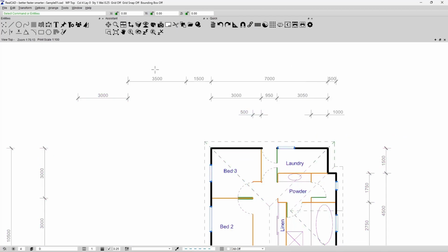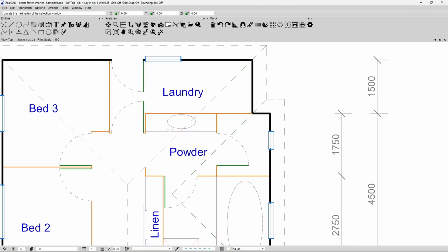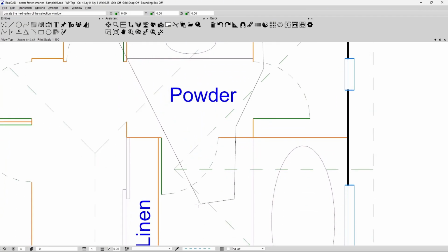In addition to being able to use a rectangle, you also have the ability to use a fence. The polyfence allows you to select objects with a great deal of care. If we zoom in here, for instance, I'll show you what I'll do. I'll click here as my starting point, and I'll just travel in a clockwise direction. I wish to grab these lines. I don't wish to have the door. I think I'll keep the powder room. I think I'd like to have this door, however.